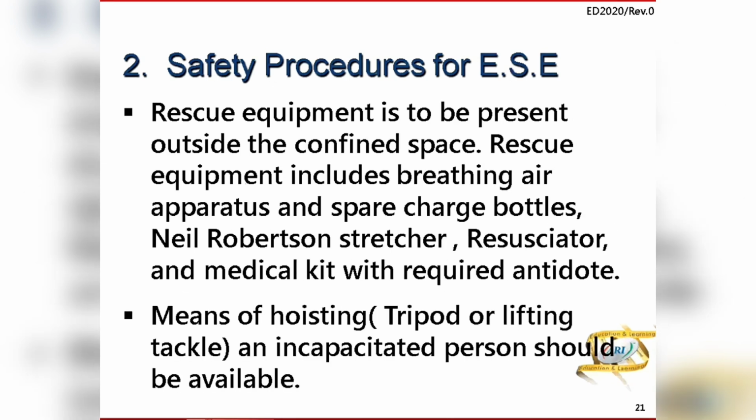Rescue equipment is to be present outside the confined space, which will include SCBA, spare charge bottles, Neil Robertson stretcher, resuscitator, and a medical kit with the required antidote for the poison there. Means of hoisting, tripod and lifting tackle, for an incapacitated person should be available.